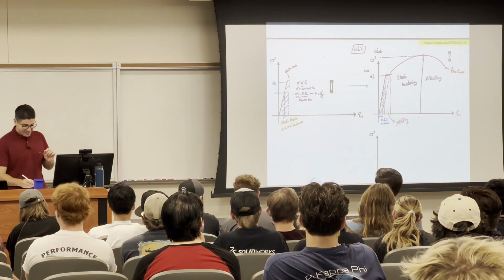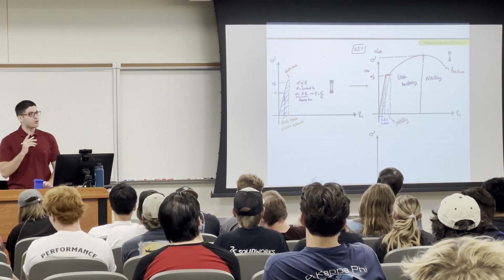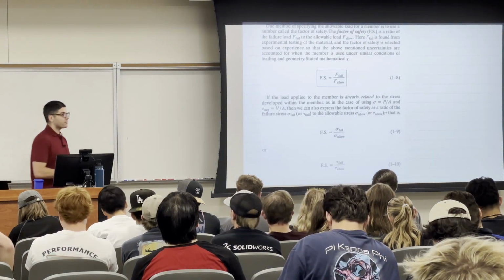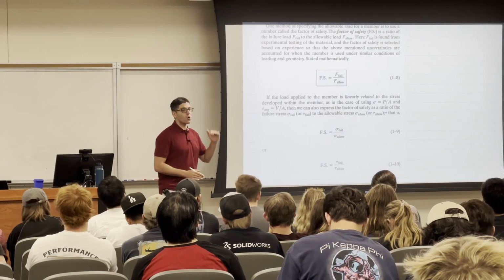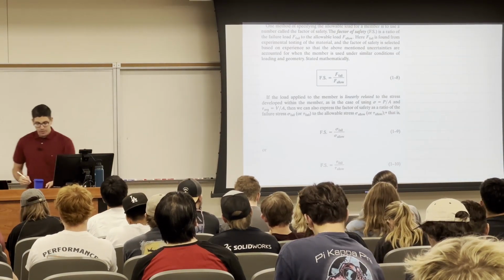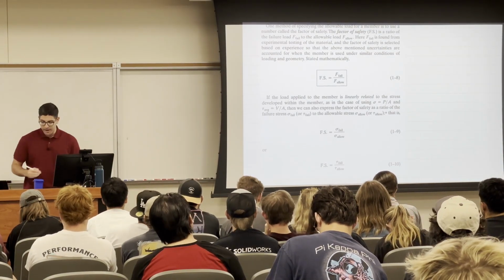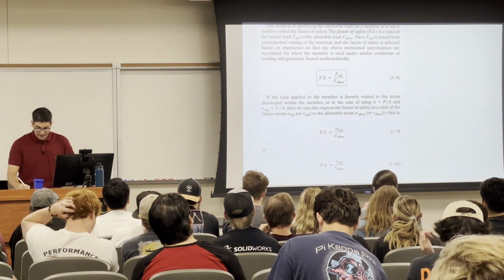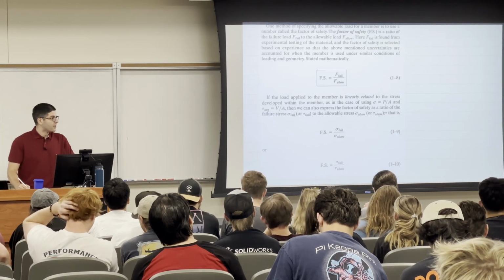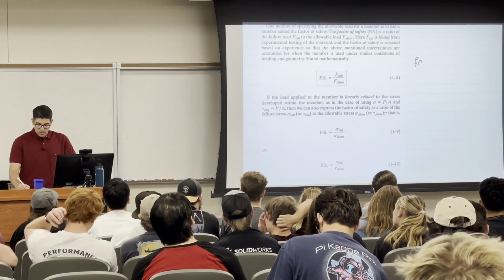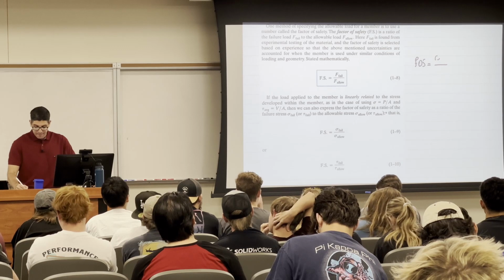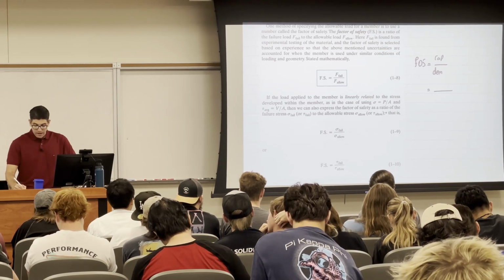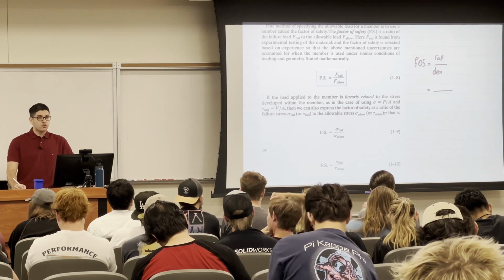Okay, and returning to the point of factor of safety, because some of you asked, the book itself explained the factor of safety in terms of stresses or loads. Some of you asked me, what if I want to apply the factor of safety on area? I couldn't find an expression or a formula for that. But if I have to guess, I would say factor of safety, you know, is capacity over demand, right? And I would say in a form of stress.